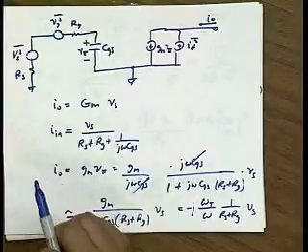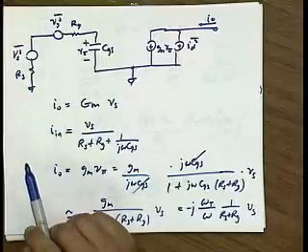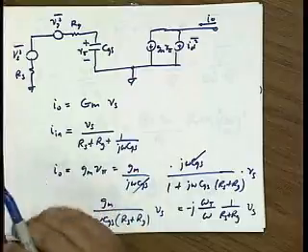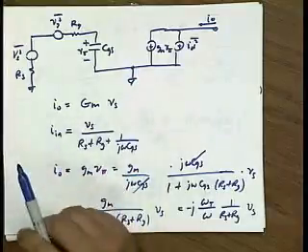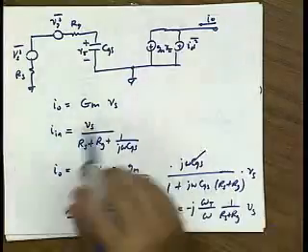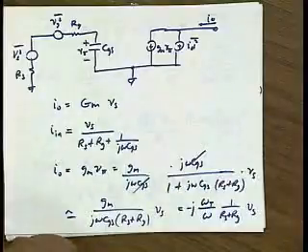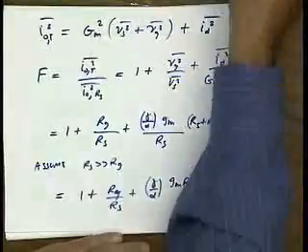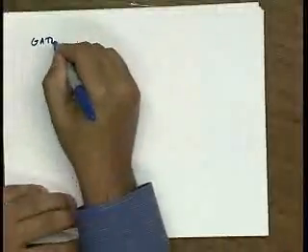Okay. Anything else? So something should be screaming at you, right? The gate-induced noise, right? We kept making a big deal about the gate-induced noise and the fact that it's correlated to the drain noise. And for the past couple lectures, I've just been ignoring it, okay? So the reason I can ignore the gate-induced noise is the following.